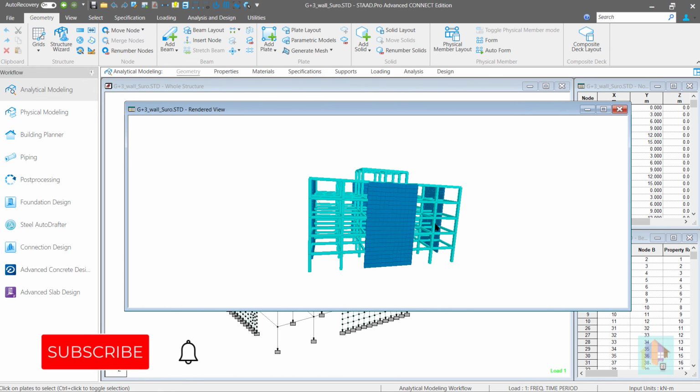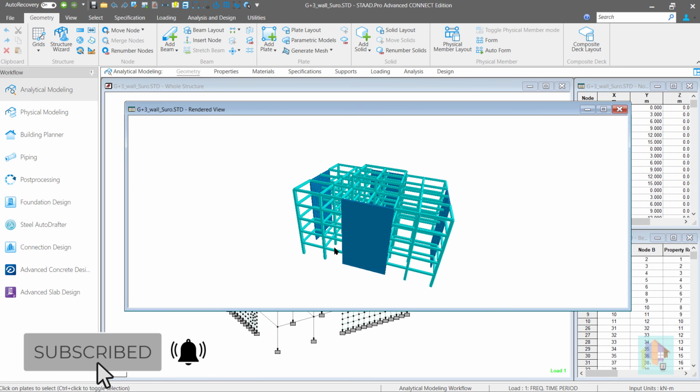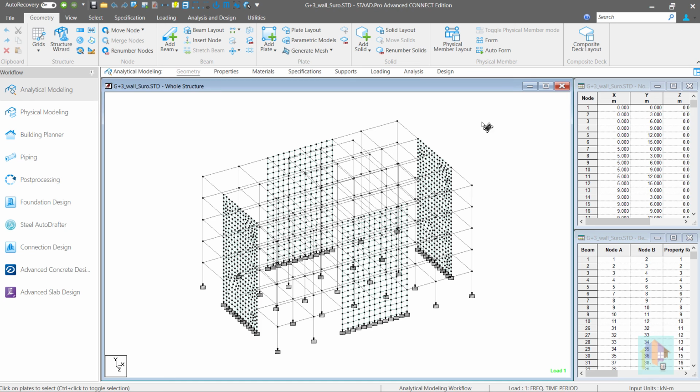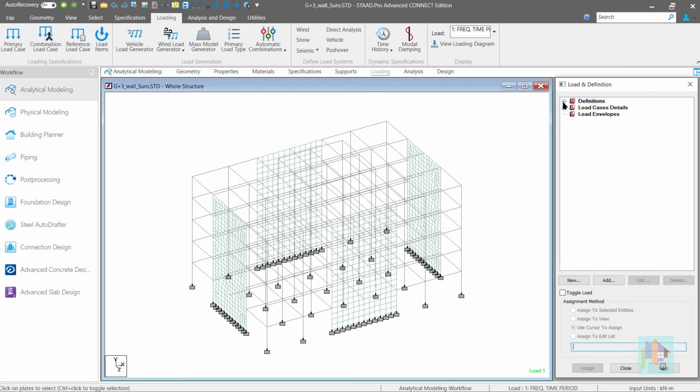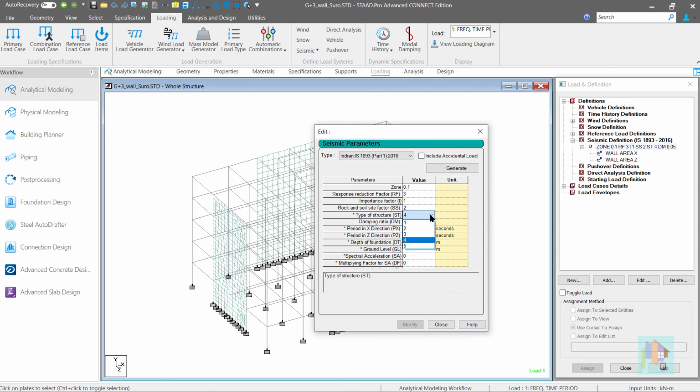So, the time period of any concrete building with a shear wall should be different from a bare MRF building. That's why a couple of equations are provided for buildings with RC and URM infill wall. We can define these conditions using the ST4 and 5 parameters, but there are a few additional inputs.